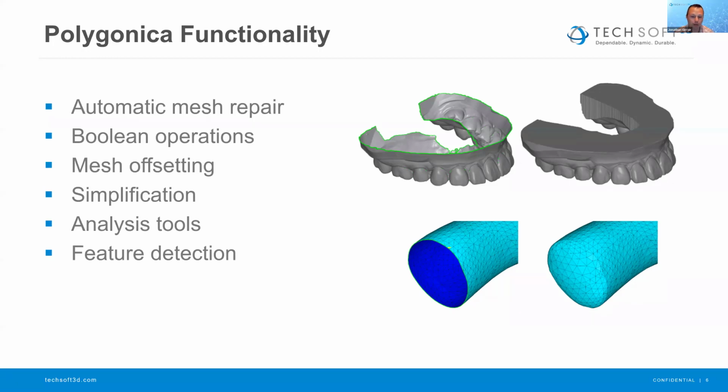But MachineWorks has been very efficient, very good at taking a mesh and modeling how, as you take a tool across a part, material is removed from it. So that's where the roots come from. They've been able to do that very quickly instead of using a boundary representation or a mathematical model. Being able to model the removal of material from a triangular or polygonal mesh, they found a way to make it much more efficient and do it in real time.